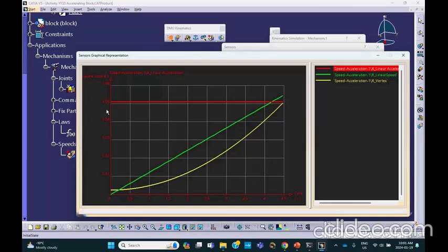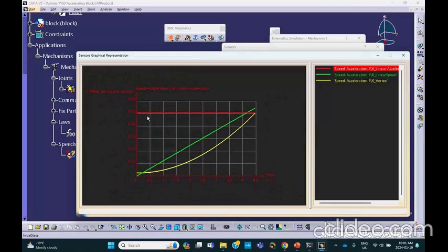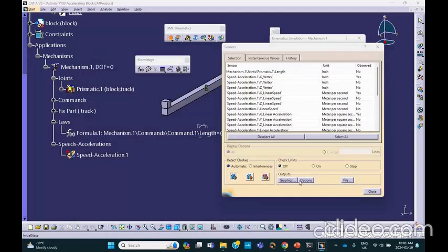So it will give you the acceleration, you ask for it, velocity, you ask for it, and position, you ask for it. The only thing is that these units are not correct. They should be inch per second squared, etc. So we're going to say no problem. Close that. Let's see if we do the units, it'll take it here.